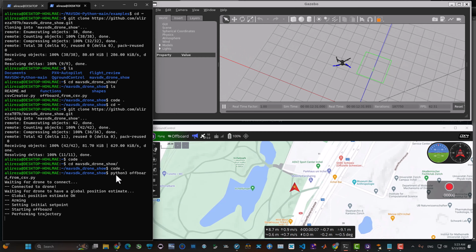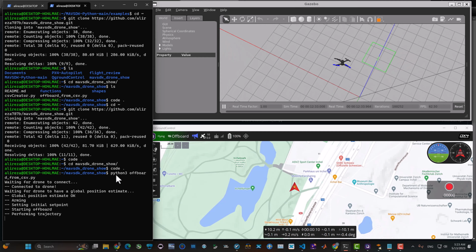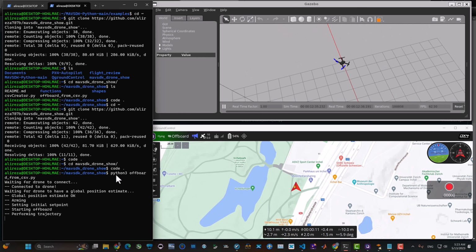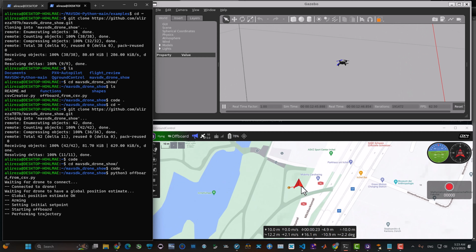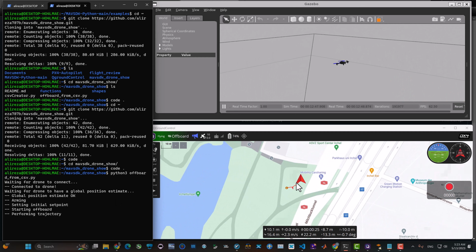Just to remind you, we are not sending the acceleration feed forwards. This makes the drone sometimes deviate from the trajectory, especially if we have selected a small diameter and a very fast maneuver. It might deviate or do some abnormal transition that might be dangerous in the real world. So make sure your maneuver time, speed, and diameter are suitable for your drone, and make sure your drone can handle those speeds and attitudes that are being commanded to it.